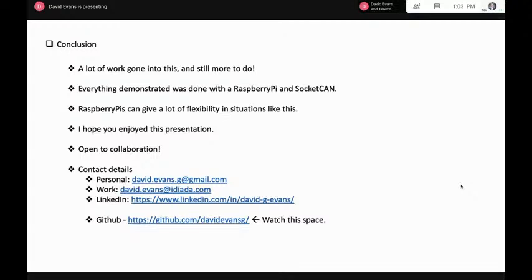So essentially, the little button module, let's call it, on the steering wheel is sending out a particular CAN message ID. Again, I think it was every 10 milliseconds or every 100 milliseconds. And essentially, the data in that CAN message was mostly zeros, or just mostly off.